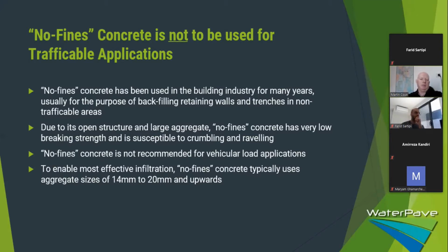It's not to be used, as I said, for trafficable applications. No fines concrete has been used in the building industry for many years, usually for the purpose of backfilling retaining walls and trenches in non-trafficable areas. Usually it's open structure and large aggregate. No fines concrete has a very low breaking strength and is susceptible to crumbling and ravelling. Ravelling is where, if you scuff your foot across the top surface, it becomes almost like a gravel, like a stone. So that's quite inherent with no fines concrete.